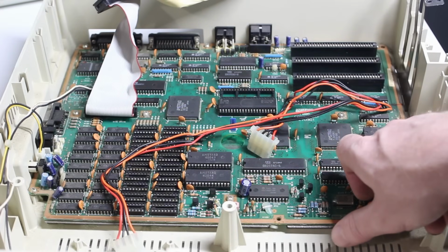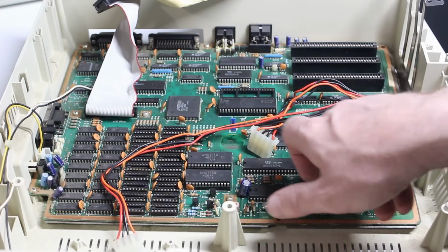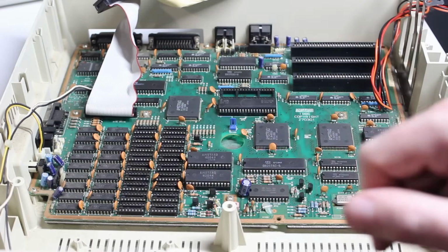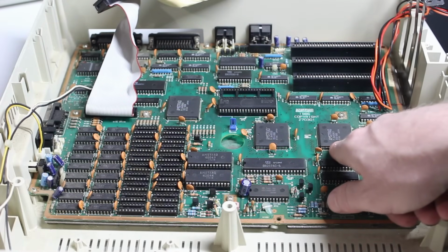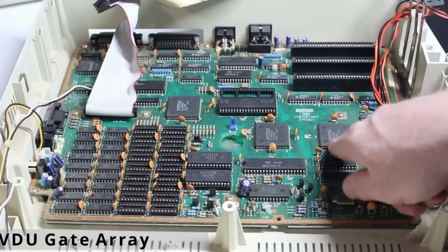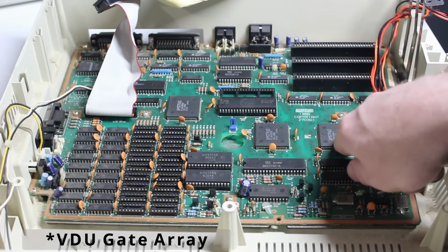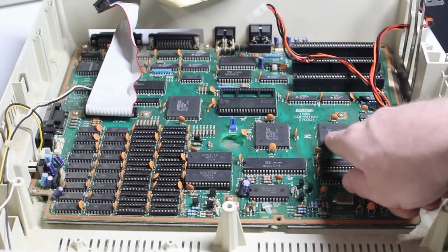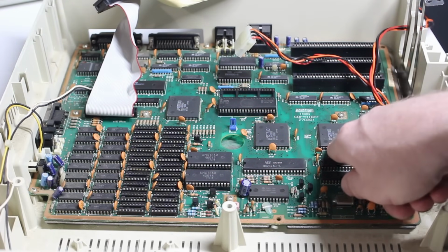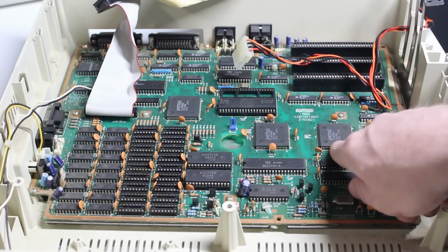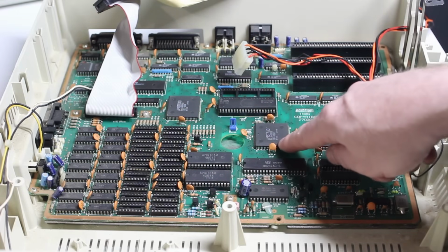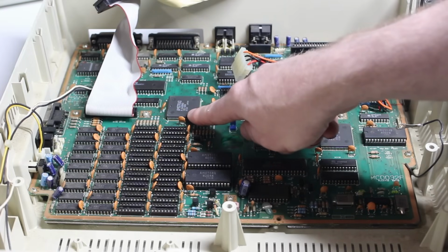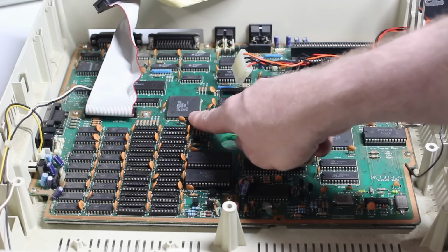There's an Amstrad 40078 character ROM, and then there are 3 chips here, the big square ones, which are the chipset for the machine. The 40041 is actually the VDU, the video display unit, in other words the graphics chip. So this is the one that we're going to try and time and figure out what it can do. It also does a little bit of other logic as well, but I won't go into any details here. There's an Amstrad 40039, that's a bus gate array, and a 40040, which is a memory gate array.